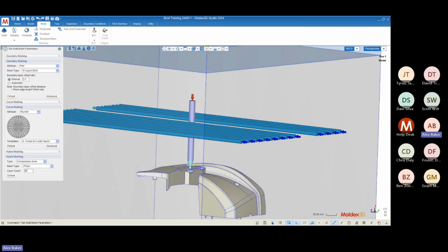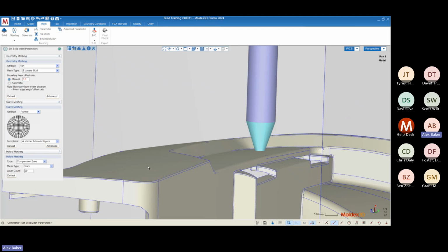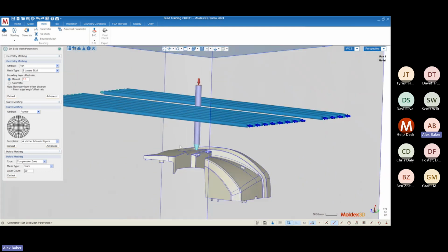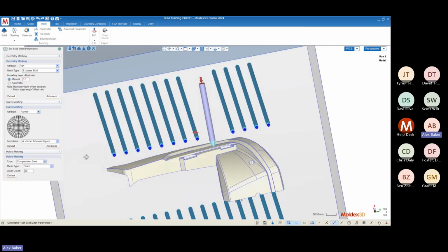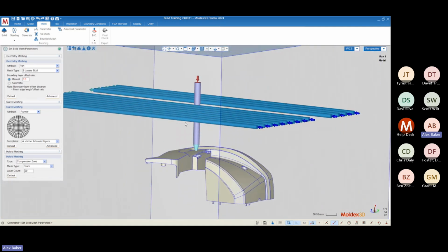Because we're using center lines, we can create a two-dimensional profile and then just extrude that two-dimensional profile along that line to create our solid mesh. Kind of like what happens in the boundary layer mesh on the part, but it happens for the entire thickness of our solid, or for our line-defined geometry.